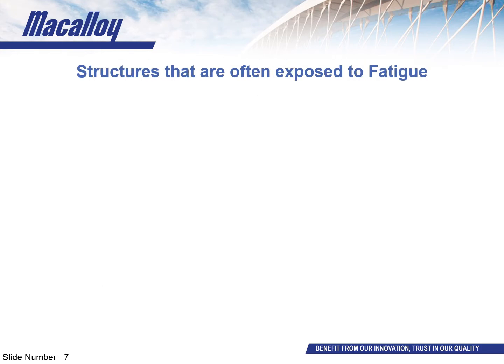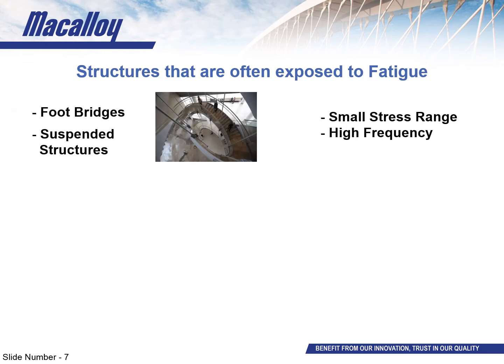By no means is this an exhaustive list, but these are a few examples of structures that typically experience fatigue. Footbridges and suspended structures such as staircases tend to have a high frequency in change in load, and this is typically as a result of the regular foot traffic that they experience. However, that stress range is often very small as it's caused by the weight of people or perhaps bicycles, so typically it's not too taxing on the material.